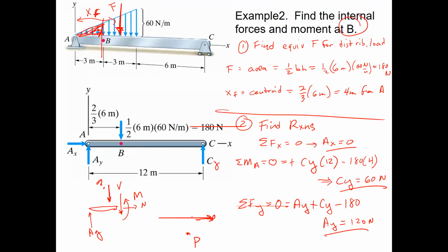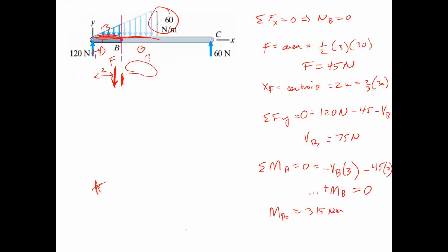You can do the moment calculation at any position along the line of action of the force and get the same moment. So that's usually what they mean by line of action. The line of action of the force extends in either direction to infinity in the arrow that it's pointing.